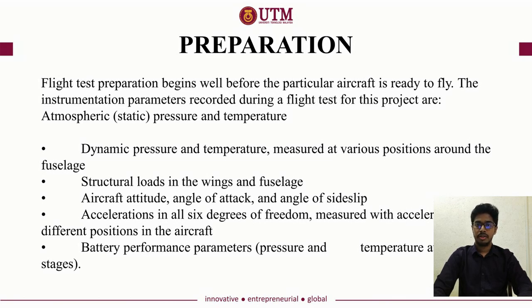The next part is preparation. Flight test preparation begins well before the particular aircraft is ready to fly. The instrumentation parameters recorded during a flight test for this project are: first will be atmospheric pressure and temperature, dynamic pressure and temperature measured at various positions around the fuselage, structural loads in the wings and fuselage, aircraft altitude, angle of attack, and angle of side slip.